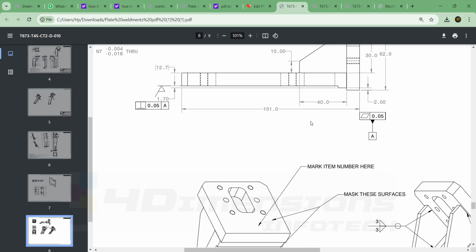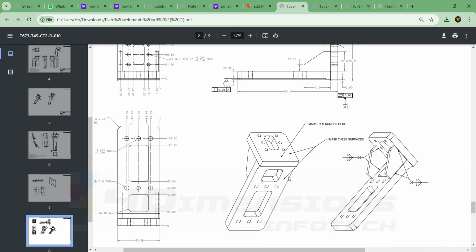Now what are the machining cuts? They are supposed to be given when any other part is to be mounted on this face. So there should not be any waviness between two surfaces of two parts. That's why machining cut has been provided here, on which the other part is going to be mounted. So whenever two plates are going to be positioned with each other in weldments, the surface of those two plates should be machined first and then only the mating should be done there. That's why these machining cuts are being provided.